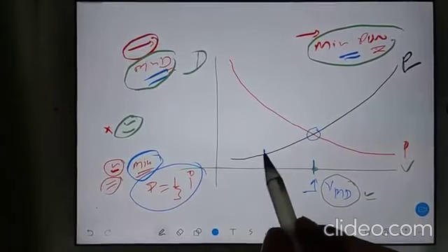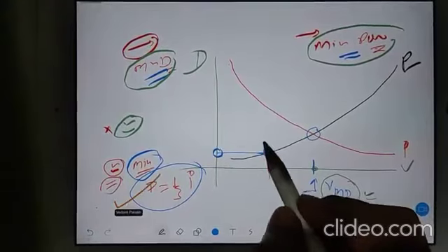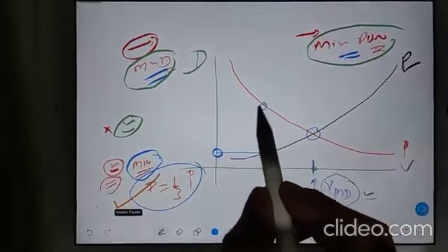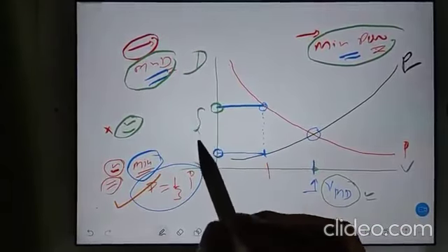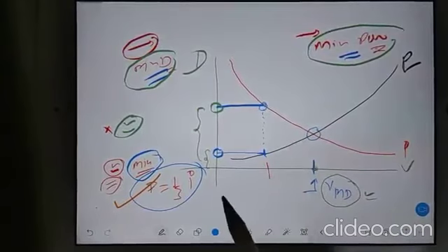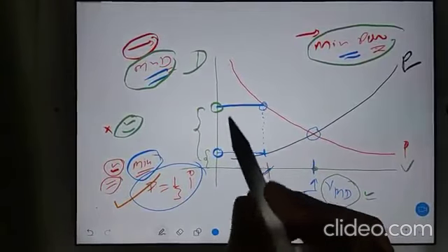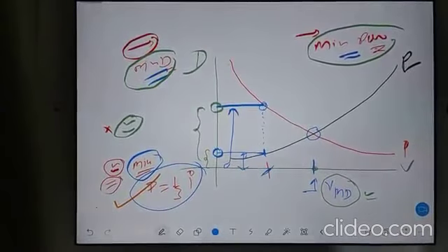You can see this graph. This graph is for the parasite drag, and this graph is for induced drag. So here you can see induced drag is larger and parasite drag is smaller. Just consider, for example, this is the velocity where it is 1/3. I mean, this height is 3 and this height is 1.